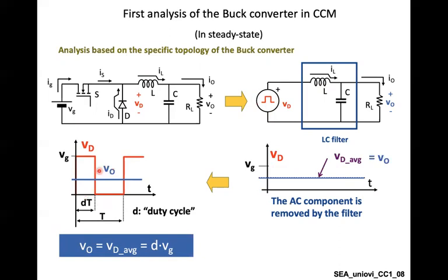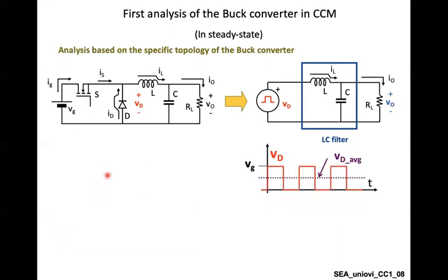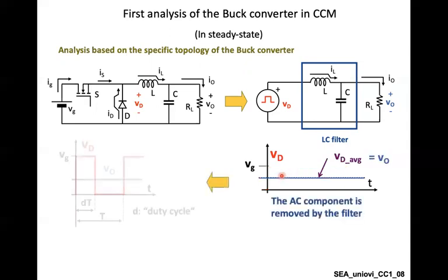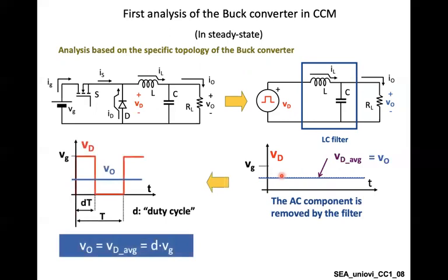So what about this average or V output? Simply speaking, the V output depends on how much time this signal will be high and how much time this signal will be low. We consider this in a factor which we call a duty cycle. So a duty cycle, simply, my students, is a ratio between the high period and the complete period.